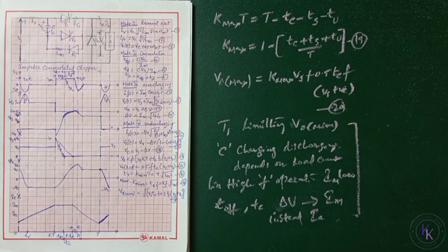An ideal thyristor chopper should not have limits like the minimum on time, maximum on time, minimum output voltage, or maximum chopping frequency. The turn off time should be independent of load current. At high frequencies, the load ripple current and the supply harmonic current become smaller. In addition, the size of the input filter is reduced. So this is regarding the impulse commutated choppers in detail.